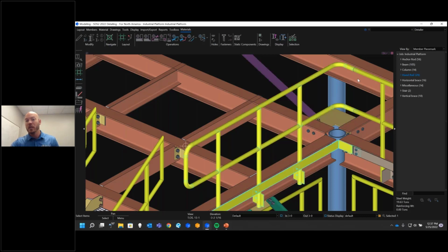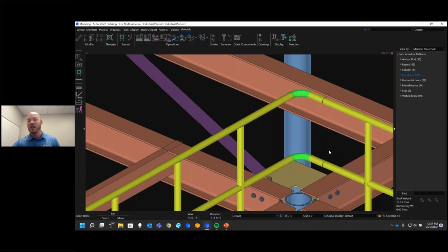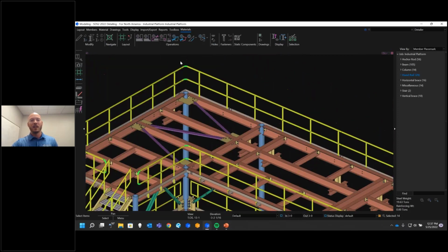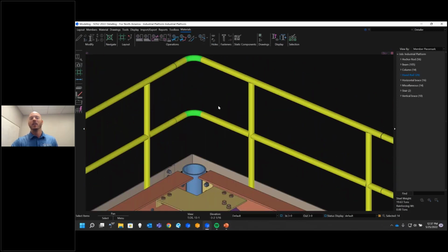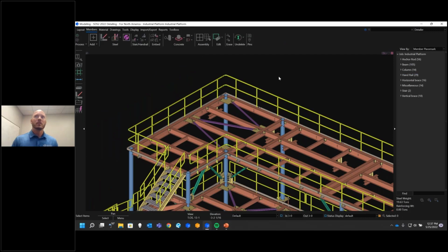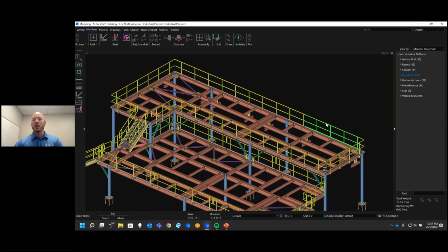Where there are identical materials, it gives them all the same piece mark. So I bet if I hit HSS 317, that's the elbows, I'm going to have some identical ones over here. You can see they're highlighted as well. So there's no post-process step to get material marks assigned. It's always done as we build this in order to keep things up to date.